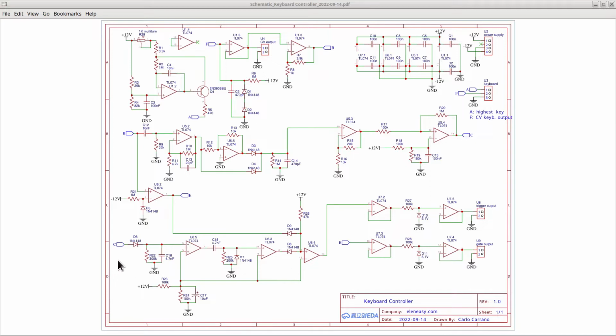The central point for the elimination of the release pulses is the op-amp U6.4, connected in a configuration that works at the same time as a comparator and as an AND gate. The AND gate is made out of D8, D9 and R26. Whenever there is a negative signal on any of the cathodes of D8 and D9, it will bring down the voltage at pin 12 of the op-amp. Only if both signals at the two cathodes are positive, the signal on pin 12 will actually be positive.